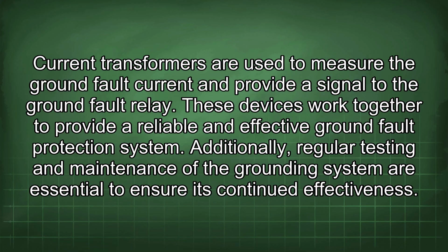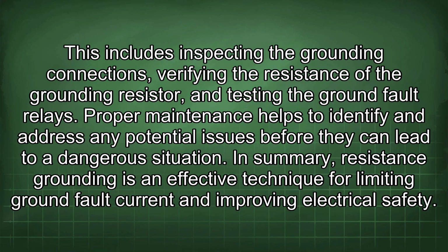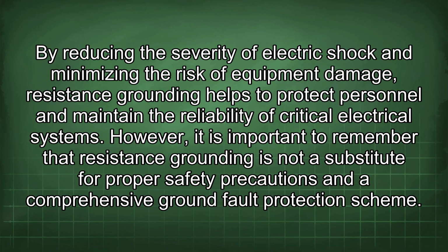These devices work together to provide a reliable and effective ground fault protection system. Additionally, regular testing and maintenance of the grounding system are essential to ensure its continued effectiveness. This includes inspecting the grounding connections, verifying the resistance of the grounding resistor, and testing the ground fault relays. Proper maintenance helps to identify and address any potential issues before they can lead to a dangerous situation. In summary, resistance grounding is an effective technique for limiting ground fault current and improving electrical safety.